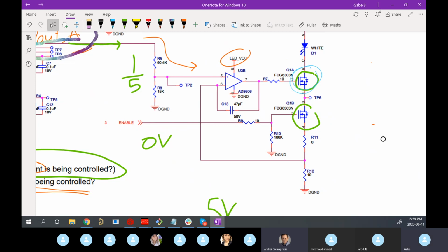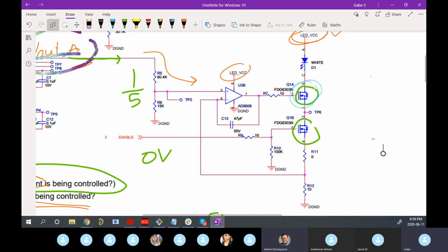Raphael already helped us a little bit. He told us that V out A coming here is stepped down by 1 over 5, right? If we had 10 here, it'd become 2. So we know that part of our transfer function is going to be this 1 over 5. We know we're stepping down whatever we spit out by a factor of 5. Right, so that's one part, and that's good. Now there's kind of this whole other part. It's kind of tricky.